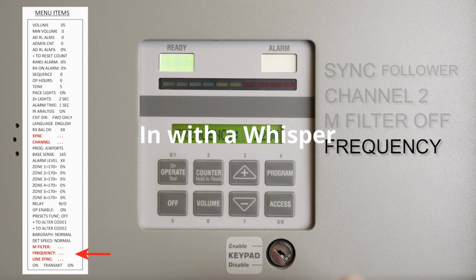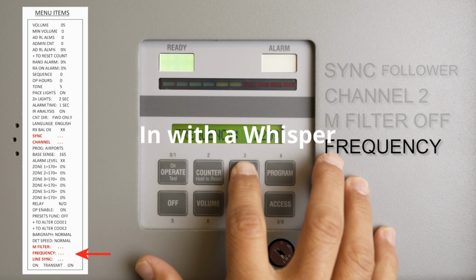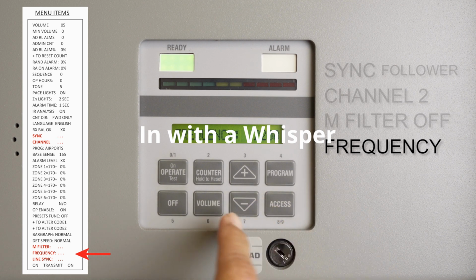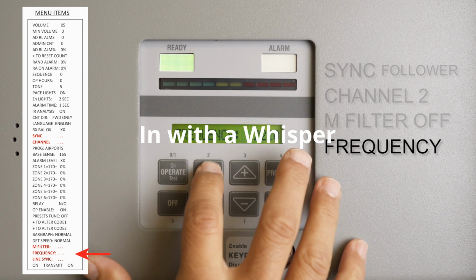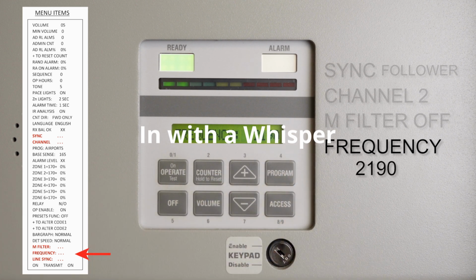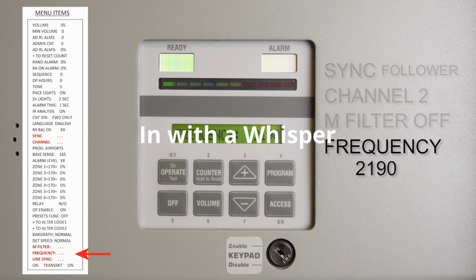Use the plus or minus buttons to modify the frequency by increments of 1. Use the counter or volume button to modify by increments of 10. Make sure to use the same frequency that your leader was set to from a previous example. In our example, our frequency was set to 2190. Our leader is also set to 2190. Using a different frequency will cause interference.